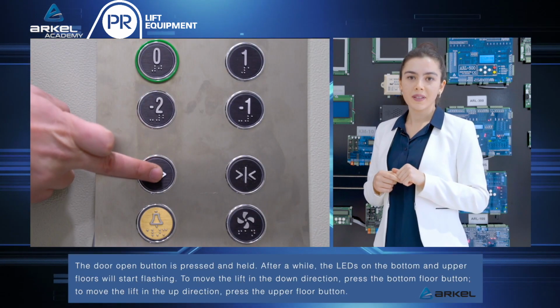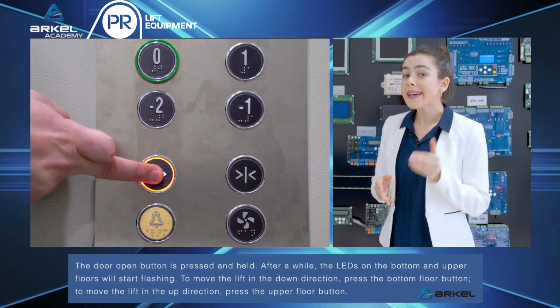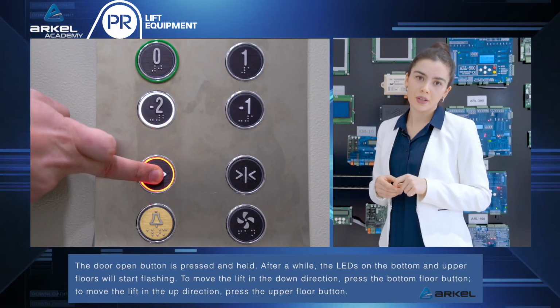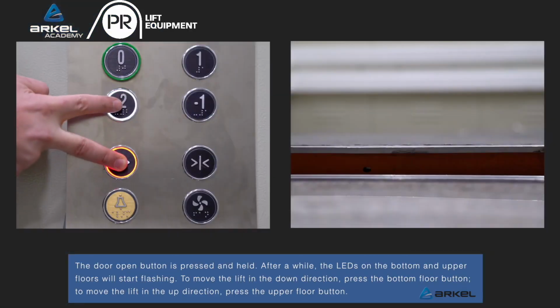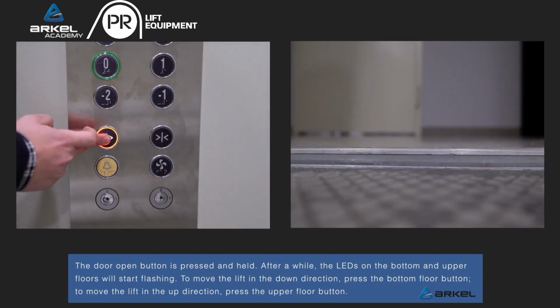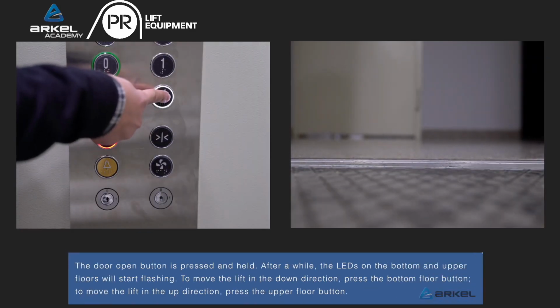The door open button is pressed and held. After a while, the LEDs on the bottom and upper floors will start flashing. To move the lift in the down direction, press the bottom floor button. To move the lift in the up direction, press the upper floor button.